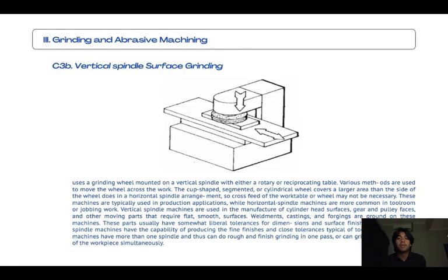The process is applicable when the part to be ground is subject to high stress in use or is susceptible to damage from heat. Parts made from materials such as high-strength steels, cobalt alloys, titanium alloys, and high-temperature nickel alloys, which are particularly sensitive to surface cracking and residual stresses from conventional grinding, can be finish ground with this approach.